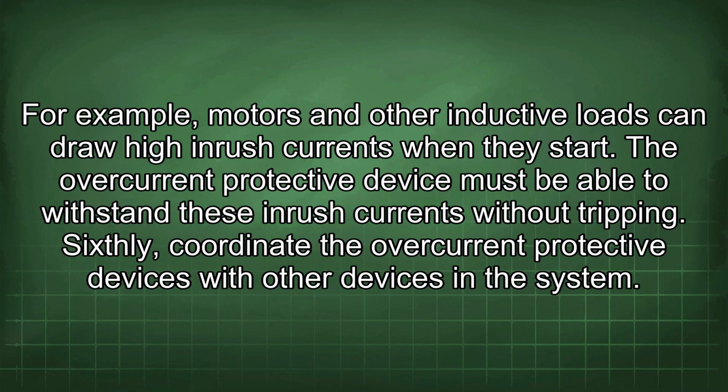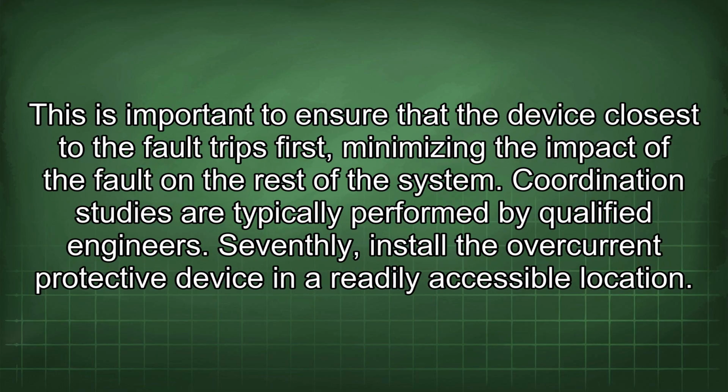Sixthly, coordinate the overcurrent protective devices with other devices in the system. This is important to ensure that the device closest to the fault trips first, minimizing the impact of the fault on the rest of the system.